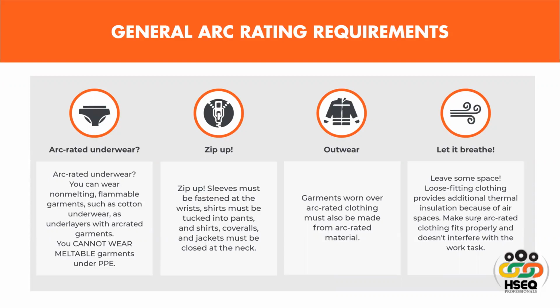So it says not to use tight fitting clothing, it uses the words loose fitting clothing, because we have seen that if we are able to create a distance in inches, the incident energy decreases very drastically. So if you are working at an 18 inch distance or at 24 inches, the incident energy is different.